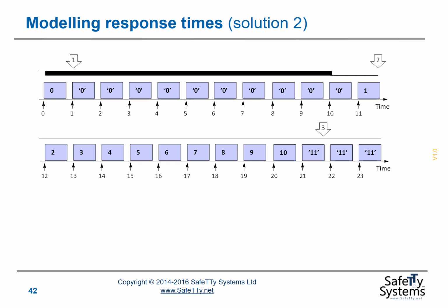So then we have to assume that the switch bounces for 10 milliseconds after it's pressed. The black line at the top of the figure illustrates the time for which the switch may be bouncing. That covers our 10 millisecond interval. What that means is for the first 10 milliseconds after the switch is pressed, we have to assume that it might be bouncing.